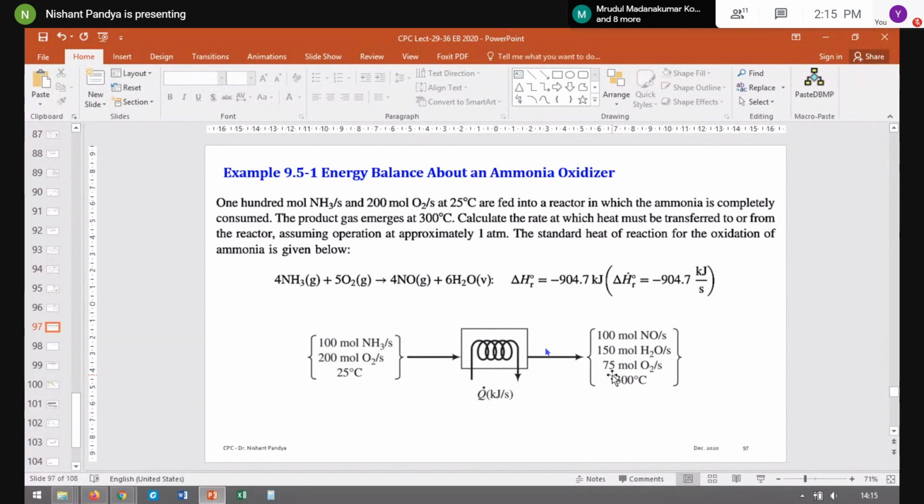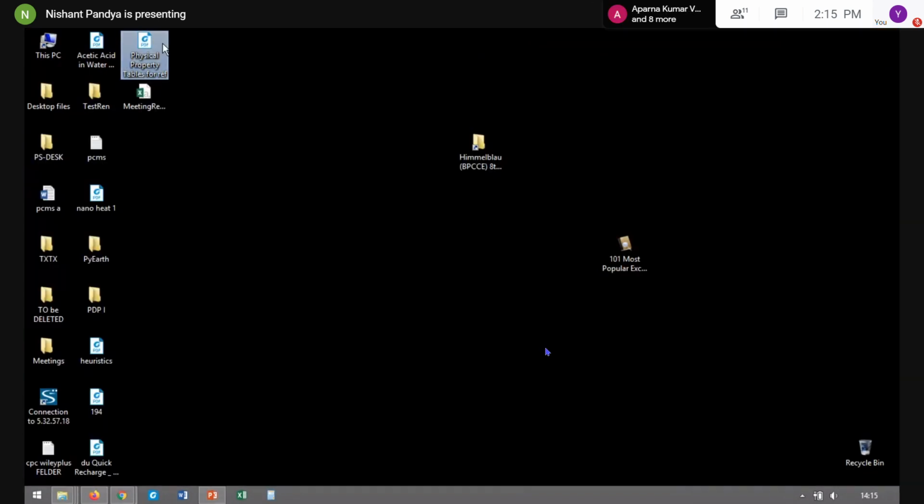Now next thing left is 3 enthalpies calculation. Enthalpy of NO, H2O, O2 in the outlet part. The other two are zero. So here I'll give the names, say for example H1, H2, H3. So this H1 is nothing but enthalpy change of nitrogen oxide, NO, from reference state to the final state. And final state here, product gases are at 300 degrees Celsius. So now you have two options. You can use the CpdT formula, or we can go back and verify if in the physical property table you have the properties given for NO.